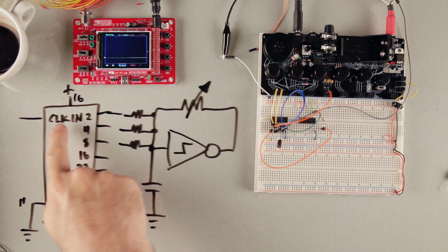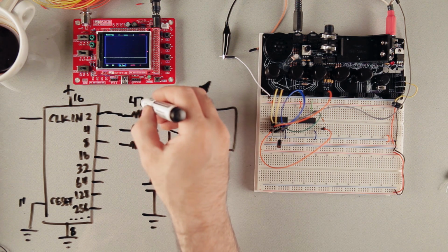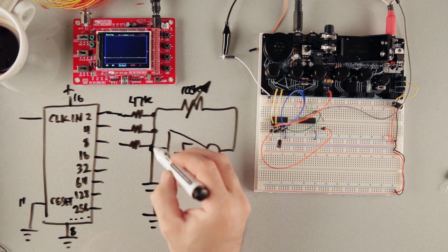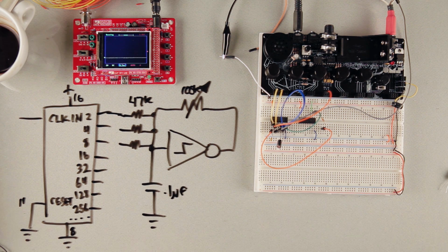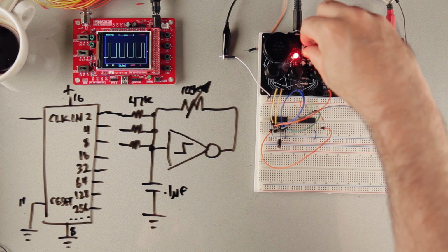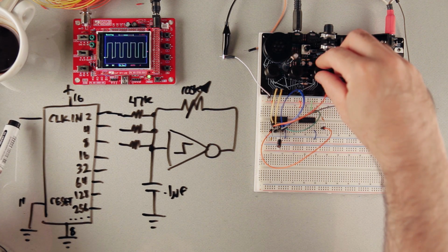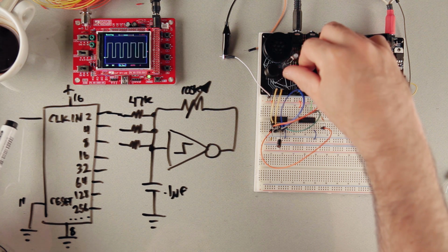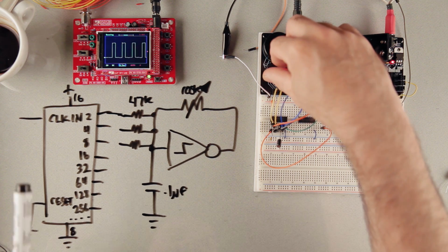Now if we take division 2 and we feed that through a resistor, we're going to use a 47K, to the base of our charging capacitor, which is 8.1 microfarad, we'll hear the pitch go up and down. And then if I change the rate of our low frequency oscillator, you can hear it going up. We can change the offset pitch.